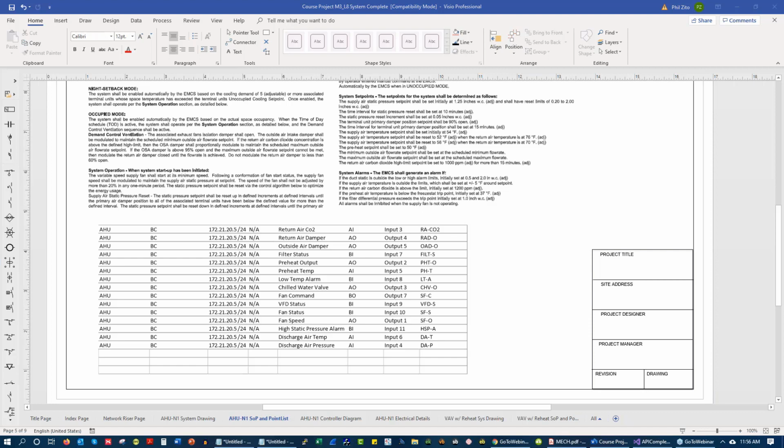All right. Do I recommend having the BAS on a virtual machine? Almost always, because virtual machines provide so many opportunities for failover. I think a lot of folks, when they hear virtual machine, get it mixed up with cloud and data center. I can run a virtual machine on my computer right here. You do not have to have your BAS server in the data center or in the cloud. You can run a virtual machine right on a Windows desktop.